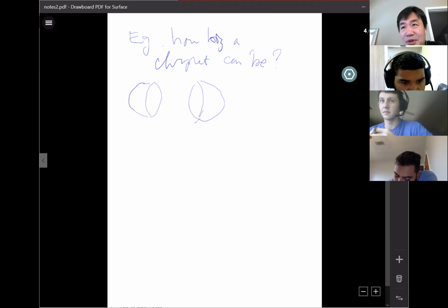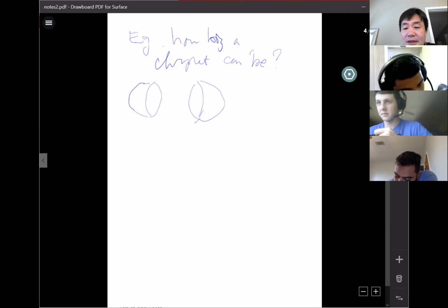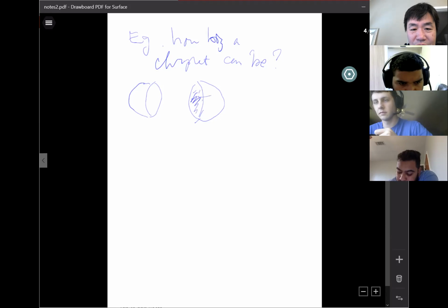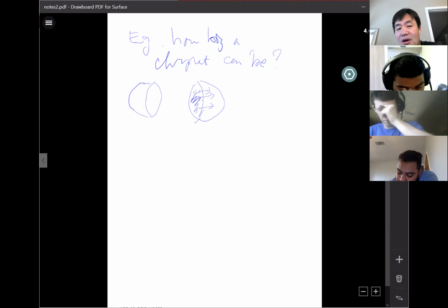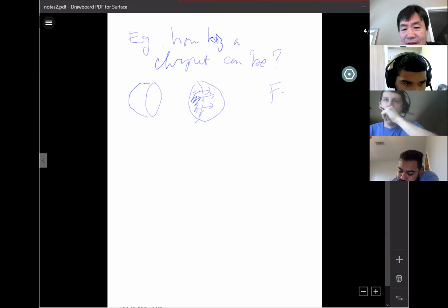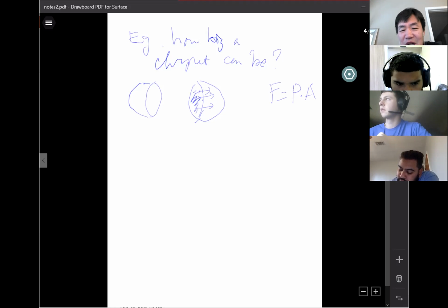The reason it breaks is internal pressure. Let's assume internal pressure is evenly distributed inside the droplet. So internal pressure is trying to break the droplet. On this surface, you have internal pressure going away from each other. Why do I say it's always breaking in the middle? Because of the force that breaks it. How is the internal force calculated? The internal pressure times the area. Pressure times area is force. So which section has the largest area? You're breaking the middle or breaking the side? When you break in the middle, the cross-sectional area is the greatest.